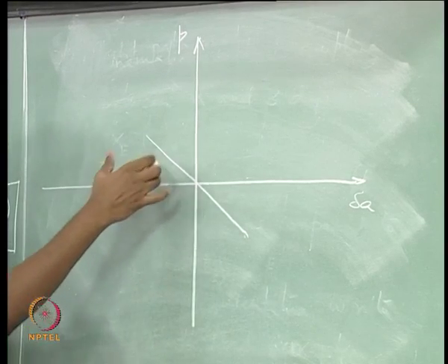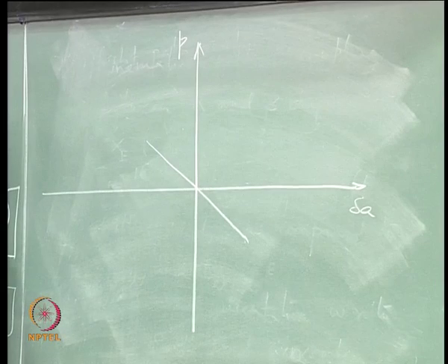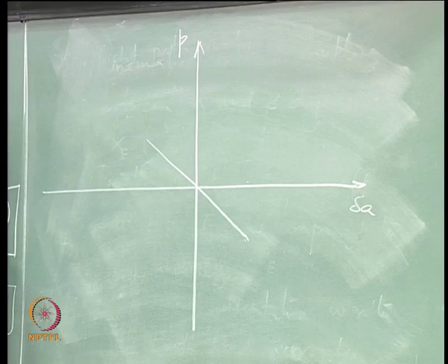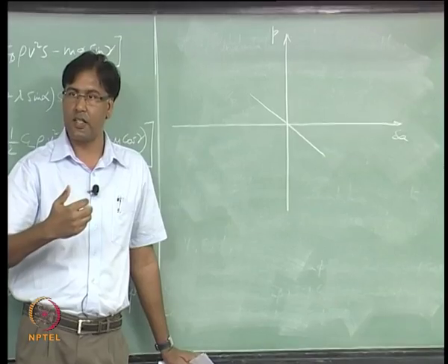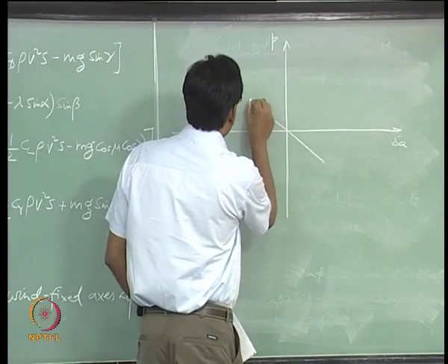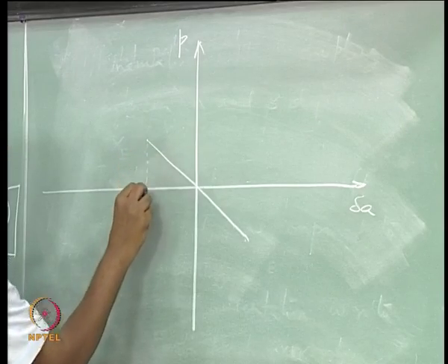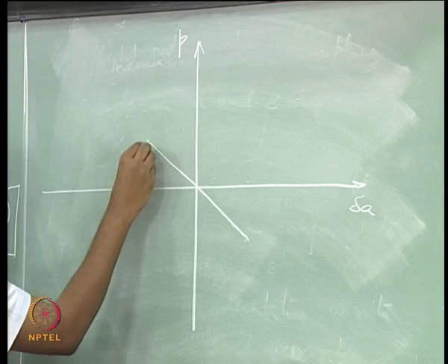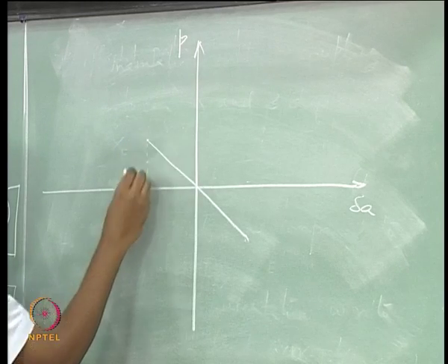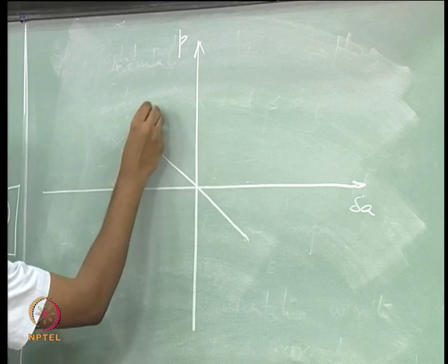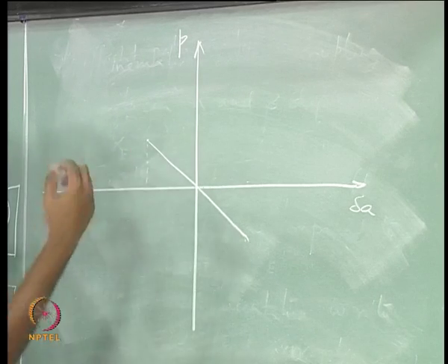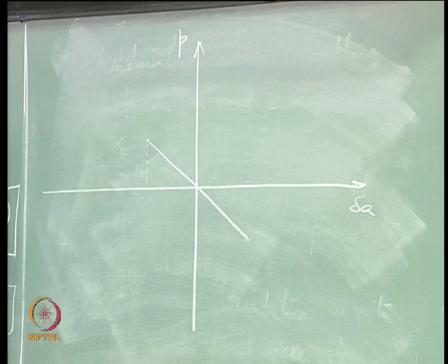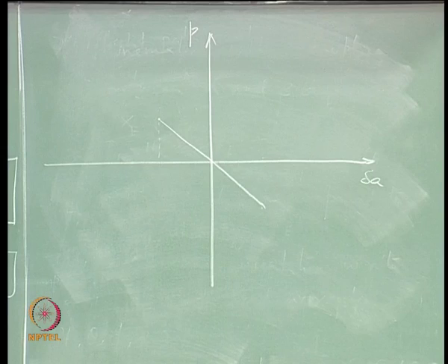So there is a positive roll, rolling to the right, when you are deflecting your aileron in the negative direction, and up to this point your roll rate is increasing linearly with delta A, which is aileron deflection. Suddenly you see that your aircraft has jumped into a situation which is giving you higher roll rate than expected, right.